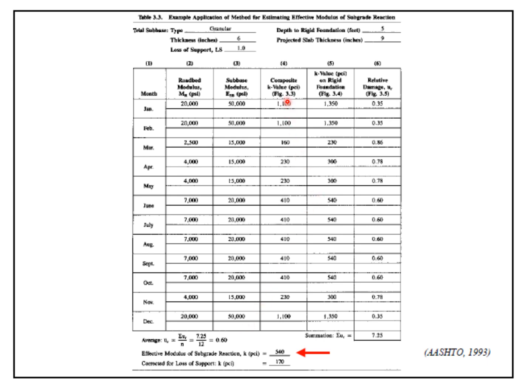Then the composite K value has been obtained by using figure 3.3, then the K value on rigid foundation by using figure 3.4, and then the relative damage by using figure 3.5. We add all these values to get the sum. This sum will be divided by 12 to get the average